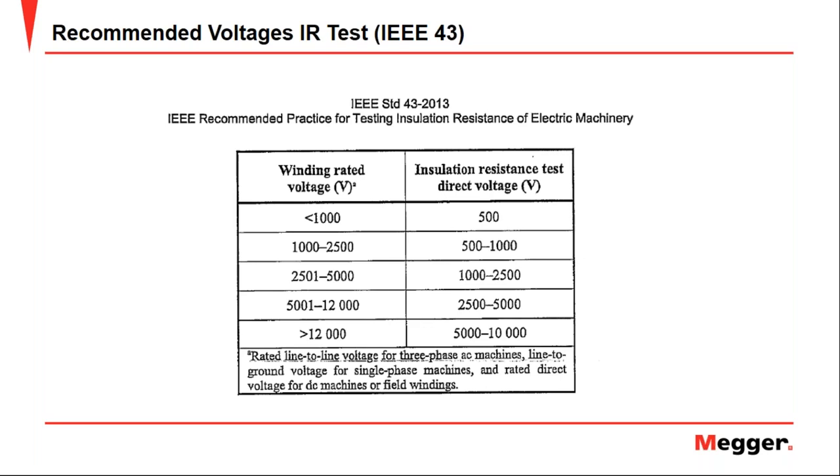Okay, and the next one is also about the rule of thumb. Does the rule of thumb of temperature, casing and winding temperature having a difference of 10 degrees Celsius apply for single and three-phase too? No, it's the same. It's the same. As long as the motor was running, that is the number that we add to the temperature reading in the case of the motor.